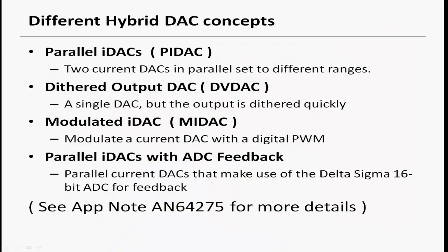Natively, the PSoC3 and PSoC5 architectures provide up to 4 8-bit DACs that can operate in either a voltage or current output mode. This unique characteristic allows you to combine multiple digital and/or analog blocks to create a more powerful hybrid component. In this case, DACs with higher resolution.